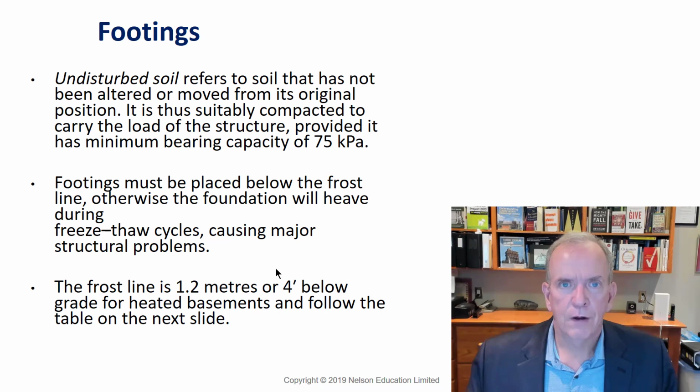In some cases, the frost might go deeper than 4 feet, in some places up north, and if you go far enough, there are even areas where there's permafrost. Although with global climate change, those areas would be questionable in some cases. But definitely, we have to fit the requirements, and so 4 feet is our minimum.